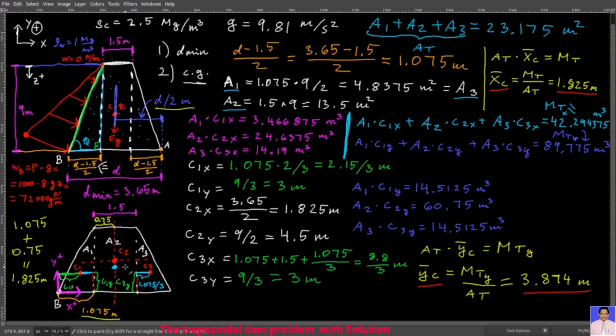And it's also the location of your center of mass and center of gravity. So the force of gravity as a point force acts through this very point, this one here. That's how you calculate the general centroid of composite bodies when it consists of multiple easier sections. You can avoid integration then.